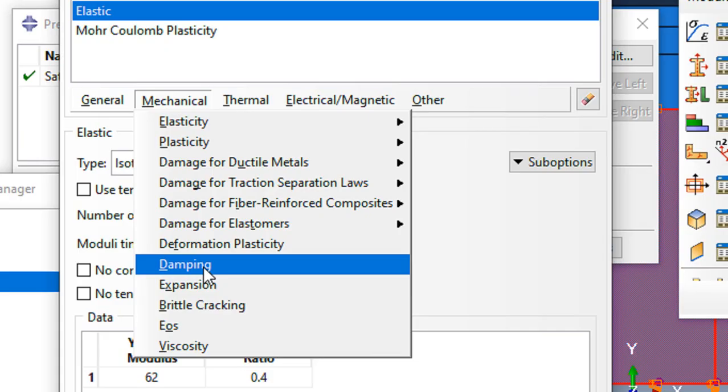Other than what I mentioned, initial conditions like initial stress in soils are also important if you are selecting your soil model. So geostatic stress is important. Initial void ratio and density are also important if you are using a material model, and initial pore pressure if it is a saturated soil. If you have a saturated soil, you can define the degree of saturation as well. And ABAQUS allows us to define these parameters.